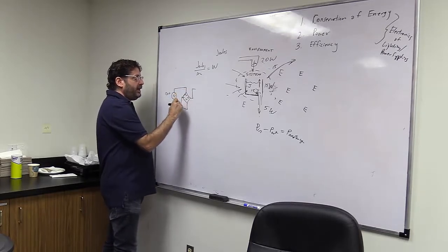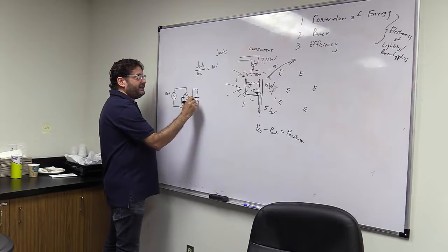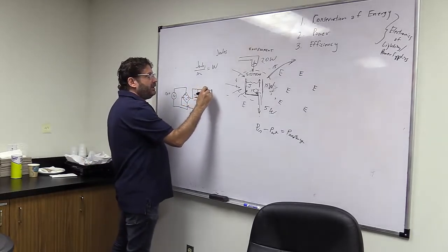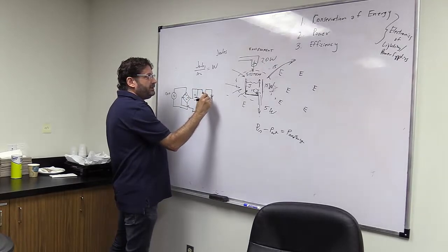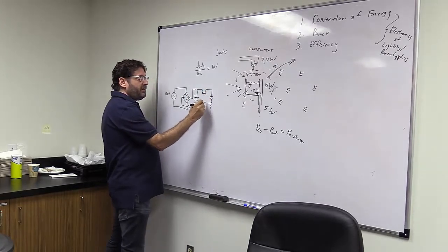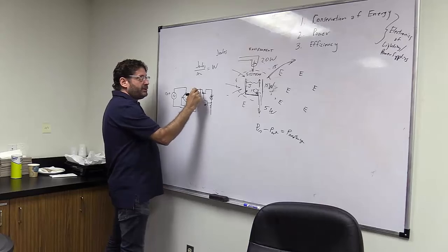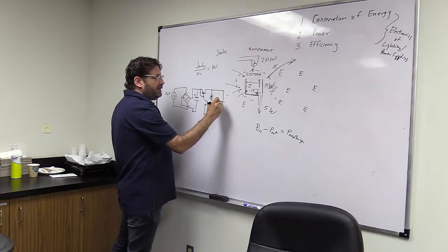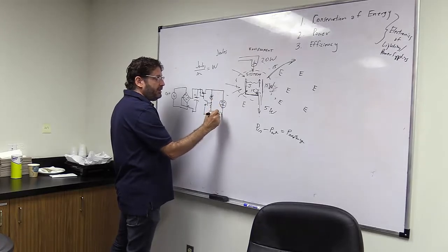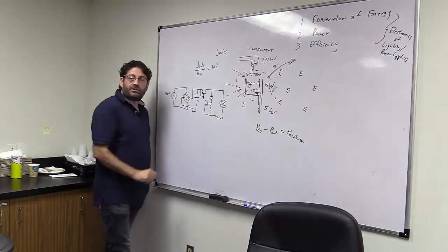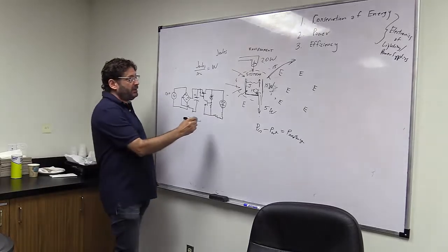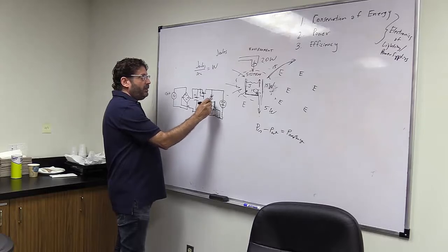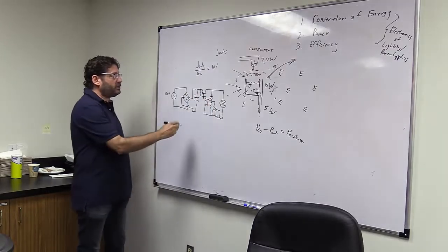And let's say that's going to a filter capacitor. Now let's say that's going to a transistor, which is going through a Zener reference, which is then coming back to a feedback transistor, which is controlling its gate. Okay, and that's feeding an LED. But the LED has a resistor in series to detect its current, and I take that and bring it back to some feedback with another transistor that I want to use to help control the gate of this to help regulate the current as well.